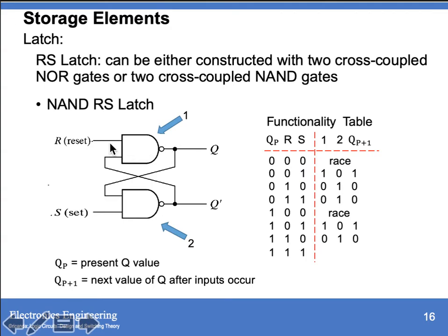So we first have to determine the value of your Q. Since Q equals 1, NAND this with 1 for your S, we have your Q bar equal to 0. If this is 0 at your Q bar, then your R is 1, NAND those two inputs, then your Q will be equal to 1. So we have 1, 0, 1.